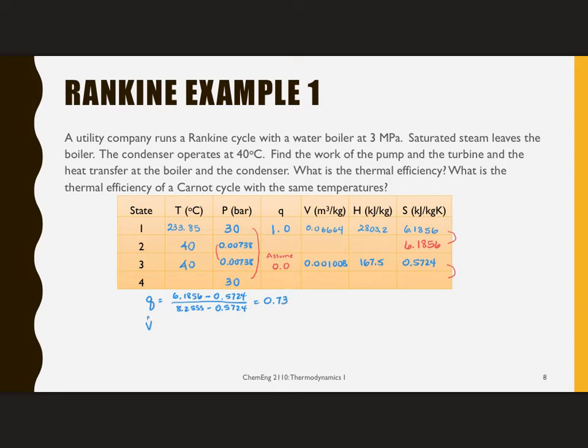I can use that to estimate V2 and H2: the saturated liquid value, plus the quality times the difference between saturated vapor and saturated liquid. The volume is 14.274.